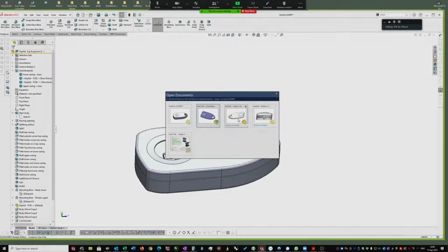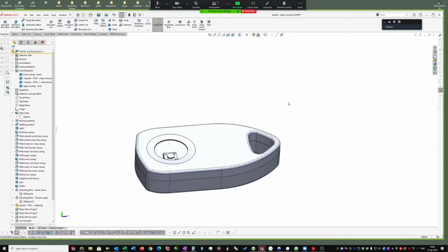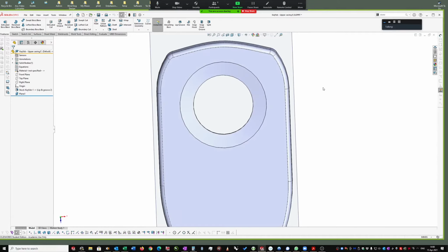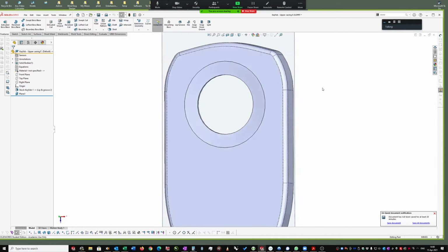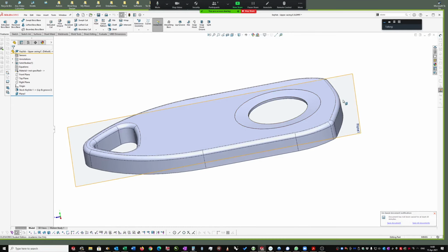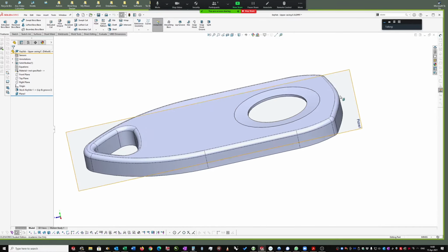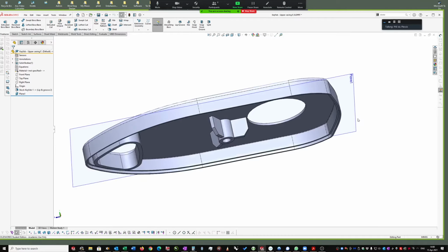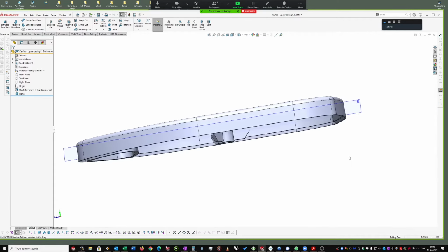That single update has gone right through to these part files. One command, you've actually updated all your parts, your lower casing or upper casing, whichever parts are affected, it will update in one shot. So very, very efficient. This is the way to do things if you want to be efficient.